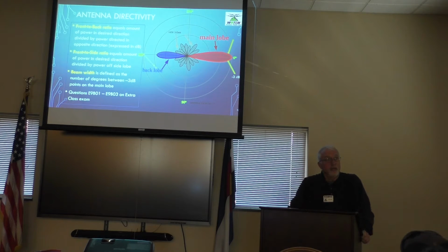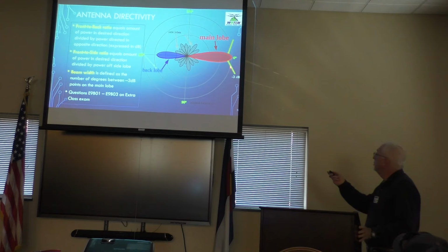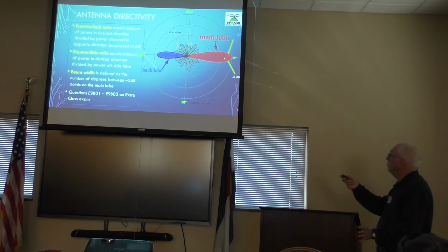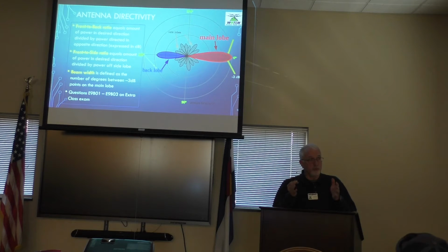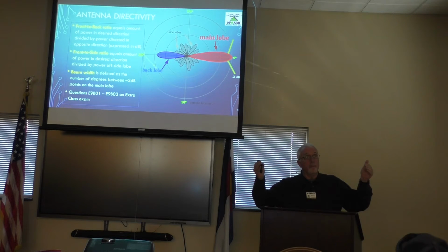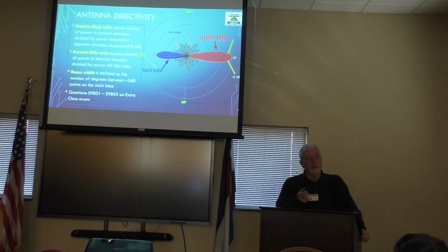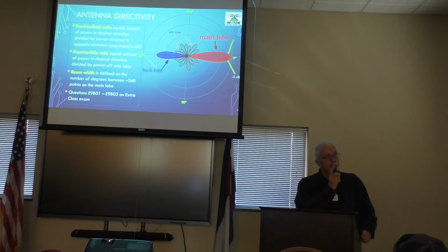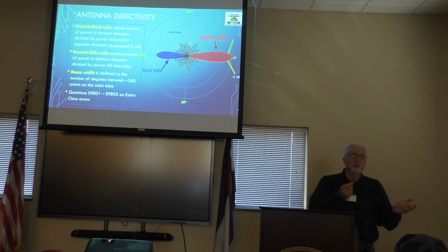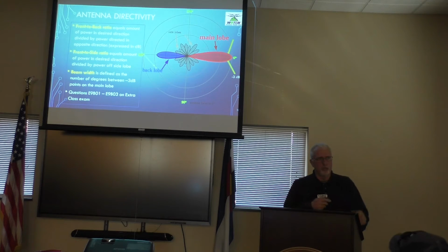Tangent, no, and actually that's a great question, because notice that we're talking about where it falls off. If you looked at the optimized frequency for that antenna, you would see a dip in the SWR at a certain frequency. Elsewhere, it's probably got a much higher SWR. So where you can run into difficulty is if the output or power amplifier driving the signal isn't matched properly, it may put out less power. From a receiving standpoint, you wouldn't care. The transmitter might not like that. We're going to get into that when we talk about some impedance matching things.